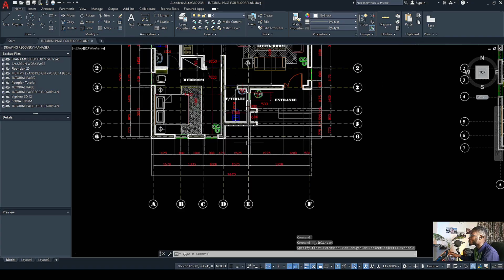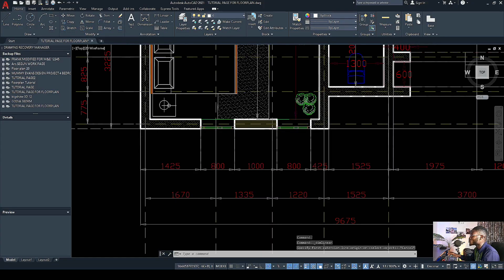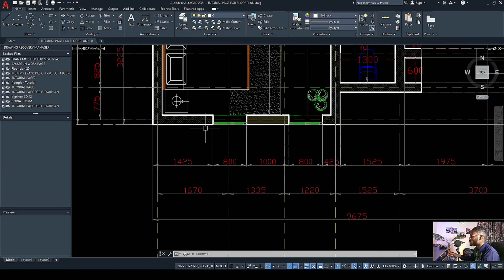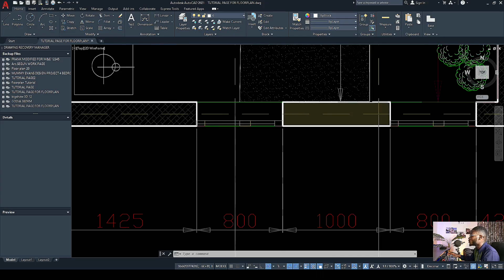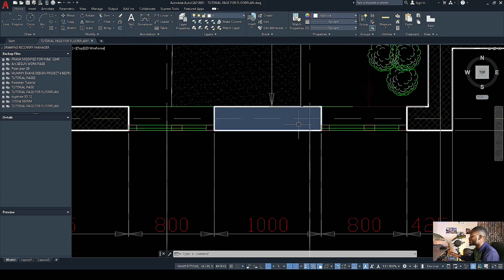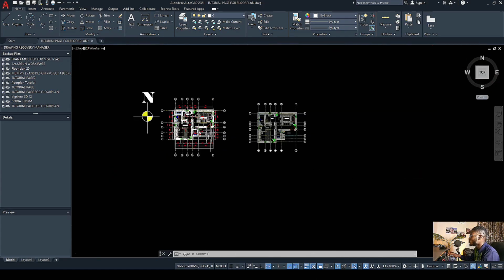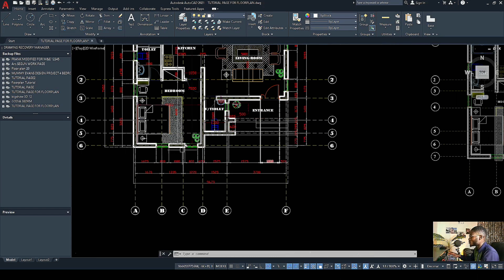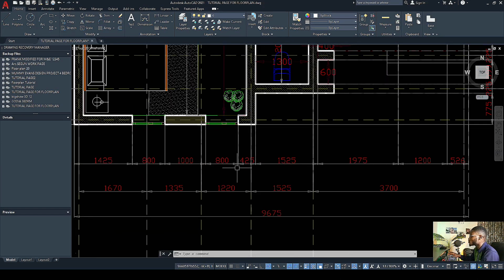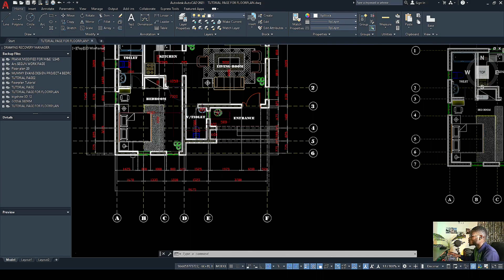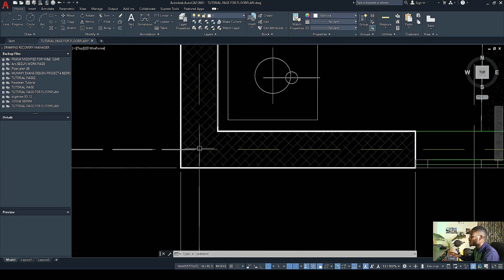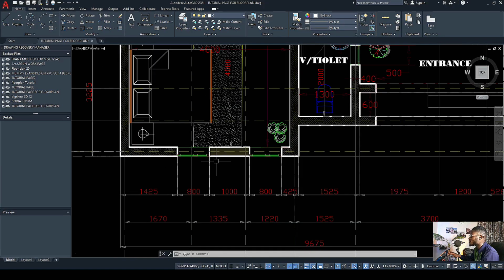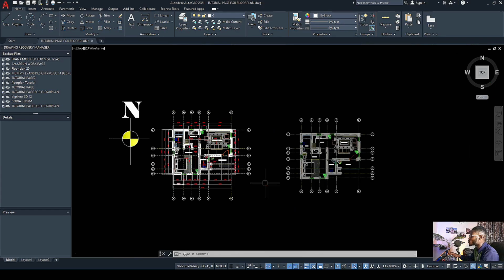I should run us through the pattern of dimensioning I did to our plan. I started by dimensioning the intervals of the external wall before each window, the partitions between each window, and also the doors, as you can see, sending all the dimensions down in this direction. So we are going to replicate the same. Then after that, I dimensioned our grid line at intervals, all the places our grid lines intersect. So we'll do that quickly.